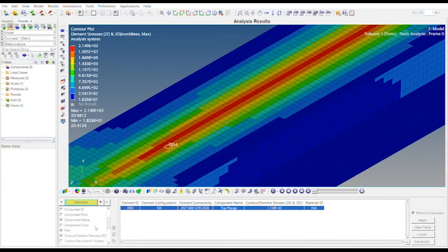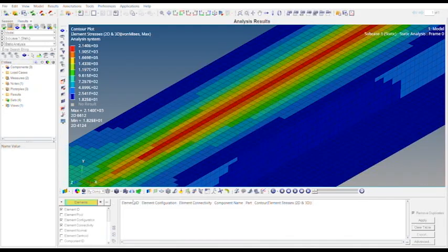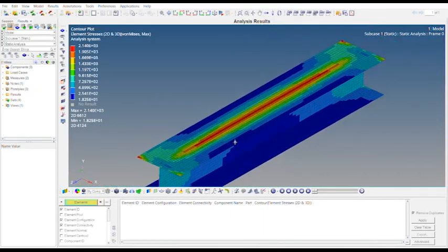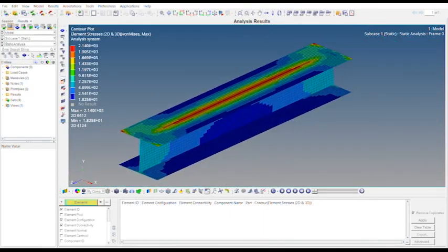Suppose we select the part, correct? And we'll click on this, correct? Okay, part is also not applicable. But this is basically for selecting the field which you want to display here. Like element ID, element configuration, connectivity, everything is selected, so it's getting displayed here, correct? Okay, so we have cleared the table now. So basically that is how you can see the exact values.